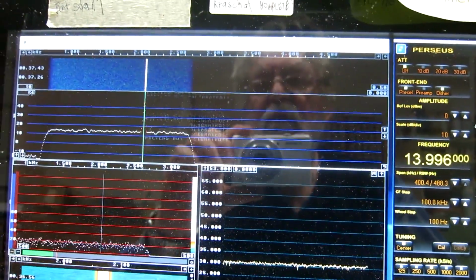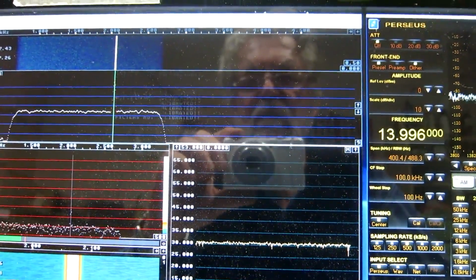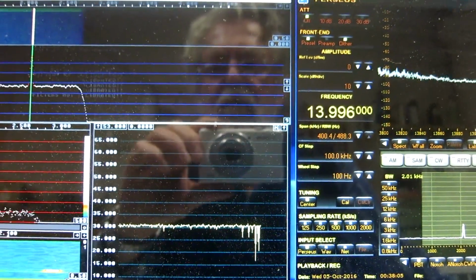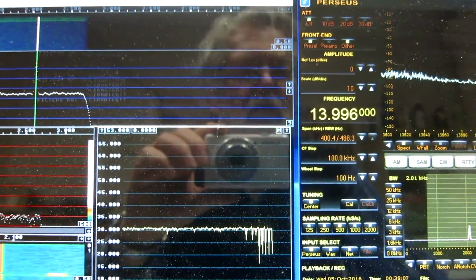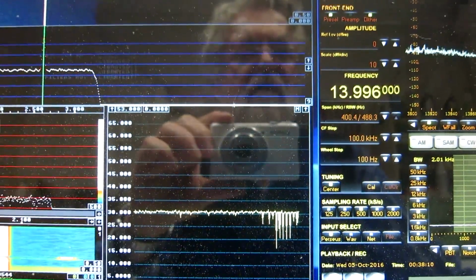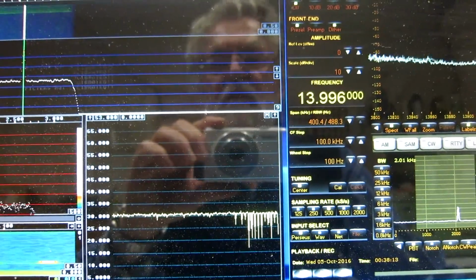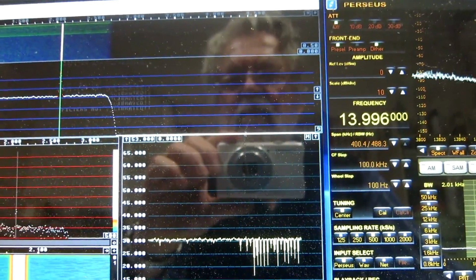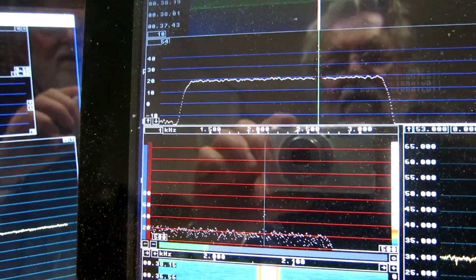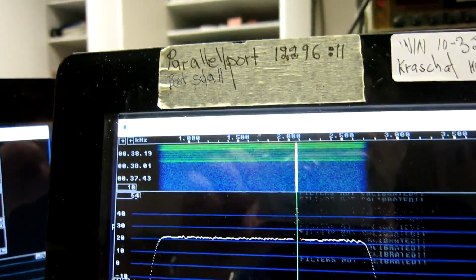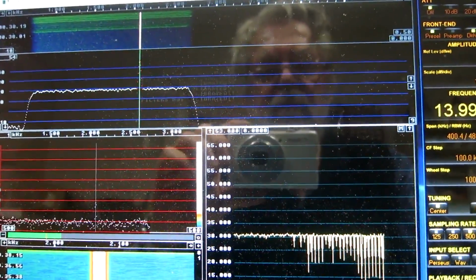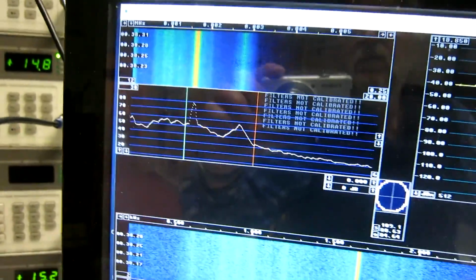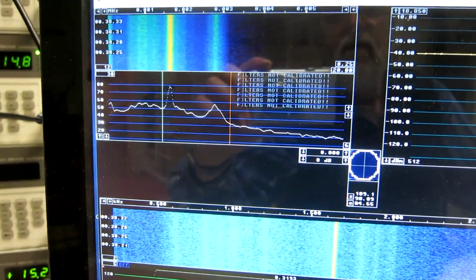But now I increase 3 dB and wait for a while, and you can see here are problems. Presumably the AD converter now goes into saturation occasionally. And 3 more dB, and it happens more often. And you can see here and in the waterfall. So here the Perseus is no longer very useful, but the ft1000 is not affected.